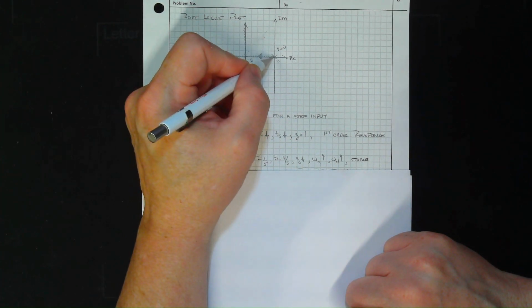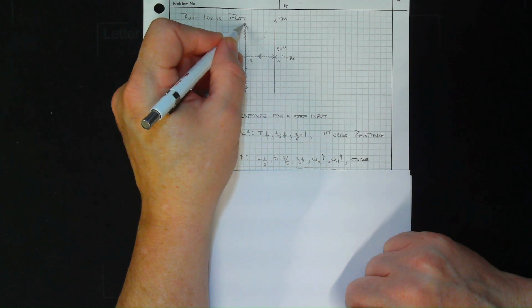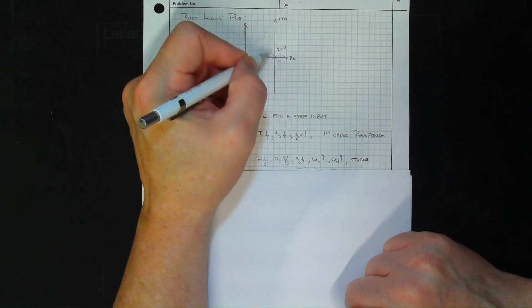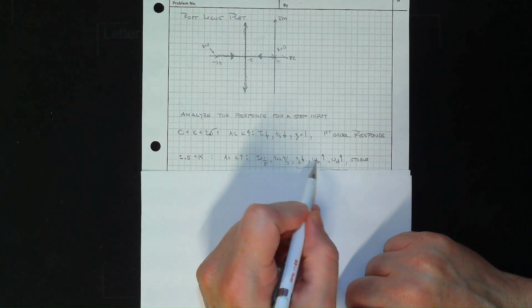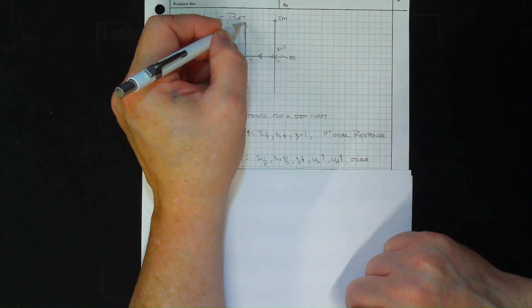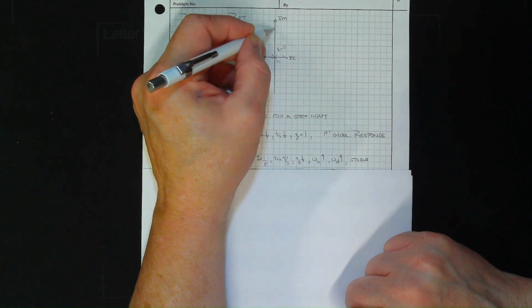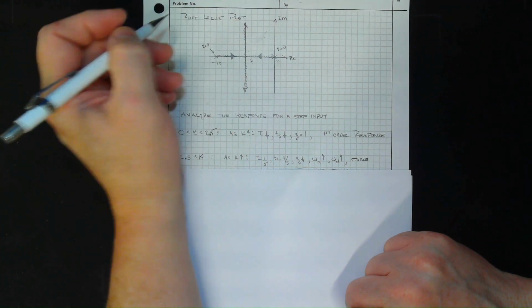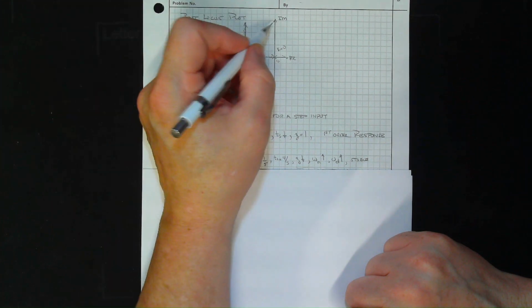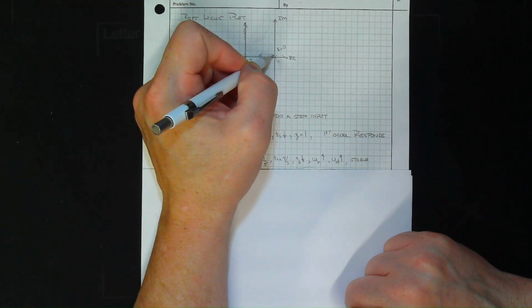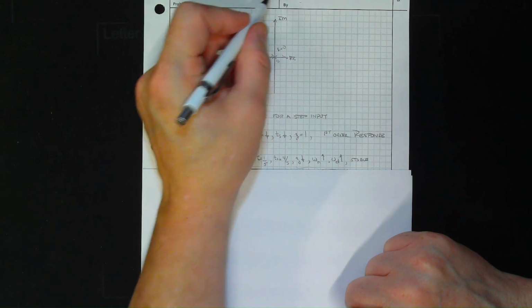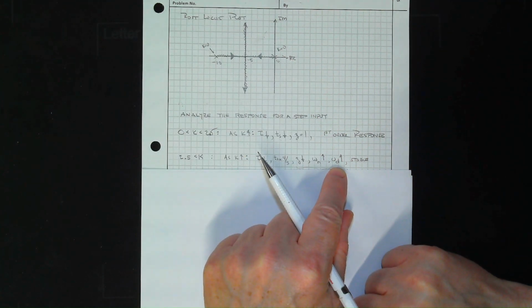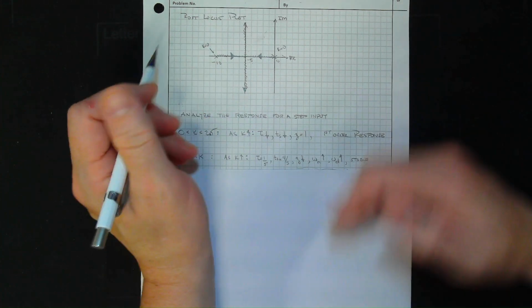Now, as k gets bigger, as this goes up here, what is happening? If you look at the distance from here to wherever this pole happens to be, it's going to keep getting bigger and bigger. So that means natural frequency gets bigger. If you look at the complex portion, which is just going straight up, that's the frequency of oscillation that you would be seeing. So the frequency is getting a lot higher. As k gets bigger, the omega d is going straight up this way. So much higher frequency.